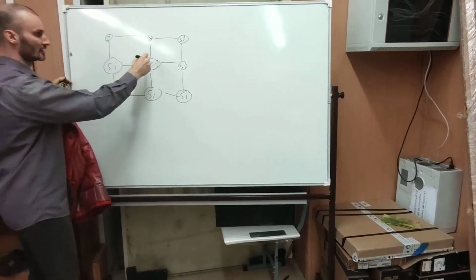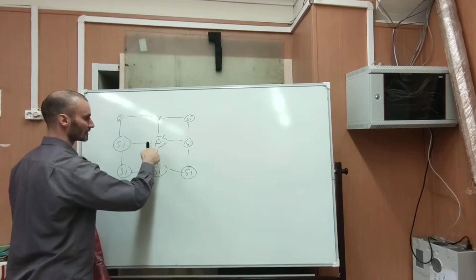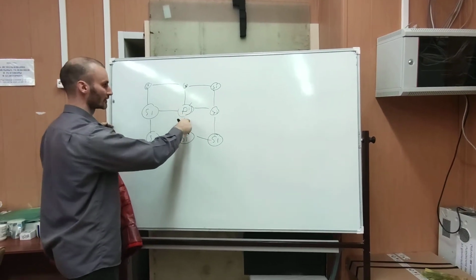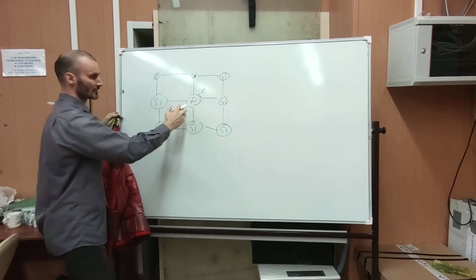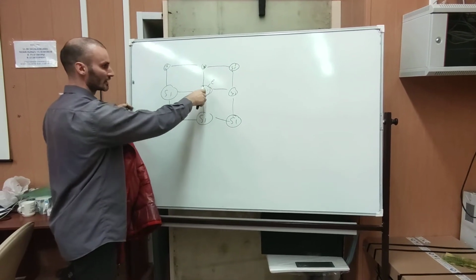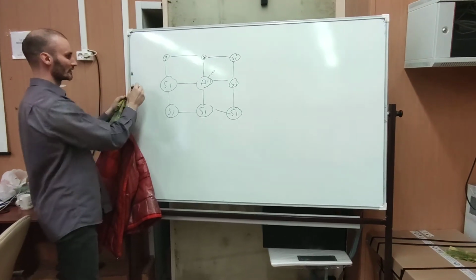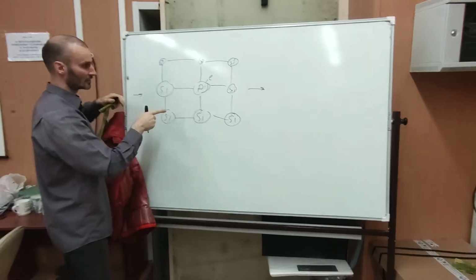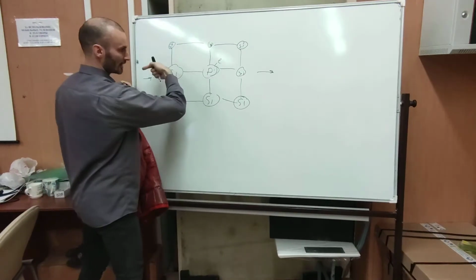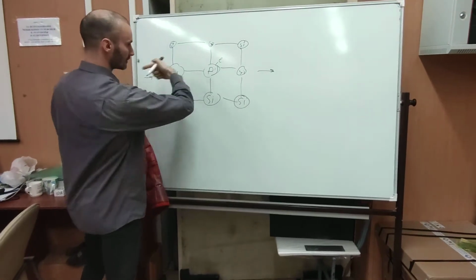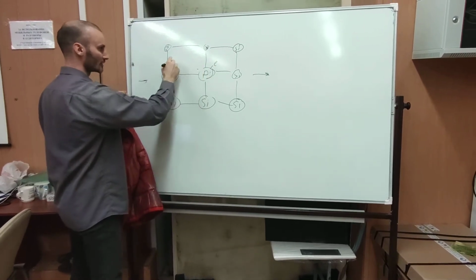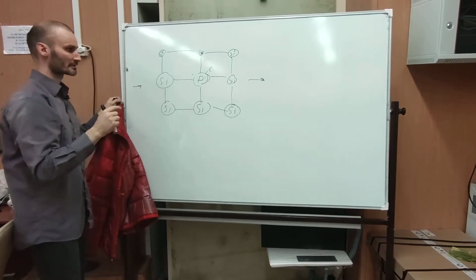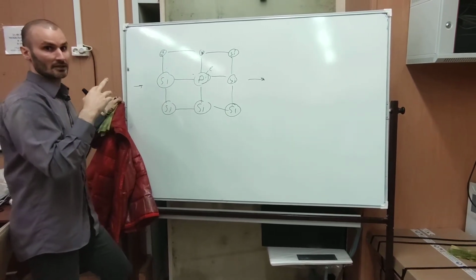So it has a fifth electron. So silicon has 4 valence electrons and phosphorus has 5 valence electrons. So it has an additional electron, and as you apply voltage in this direction, you tell the electron to go this way. So voltage this way, electron goes this way, and that electron jumps from here to here, then jumps this way and this way. Adding just a tiny bit of phosphorus makes the semiconductor conduct.